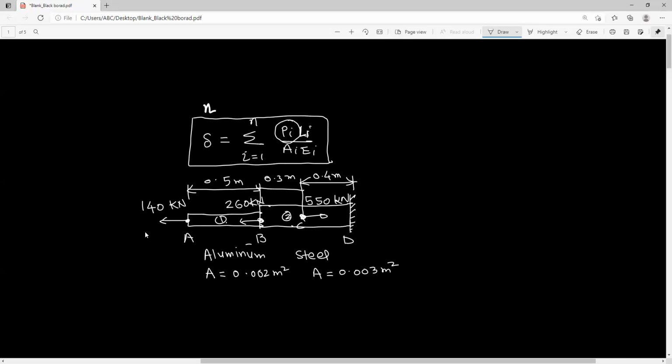It is very clear that we are required to first calculate the internal force. So first let us take the free body to calculate the internal force. How do you calculate it for the first part? Of course, there is a reaction, and the reactive force is not known to us. So we start from the left hand side, where the information on the forces is known to us.